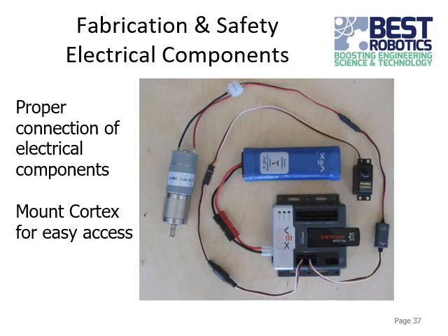Okay, onto some electrical components. Make sure everything is properly connected first of all. I'd say make sure polarities are matched up correctly, so that means red to red, black to black, that sort of thing. Also, make sure everything is secure in its connection, so it's not going to fall apart when it shakes a little bit or have an intermittent connection.